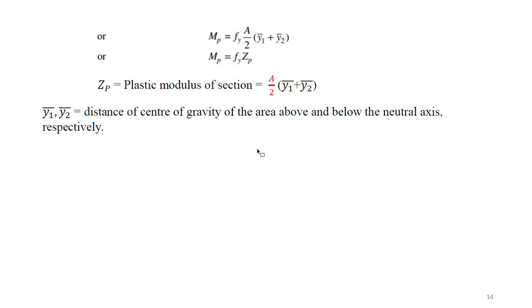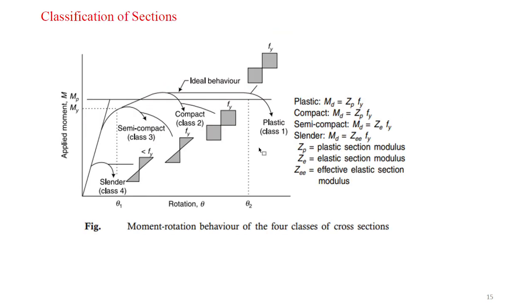This is regarding the plastic moment of the section and the plastic modulus of the section. Now, depending on the nature of the sections, on the stress strain, moment rotation or moment curvature diagrams, we divide these sections into four classes.